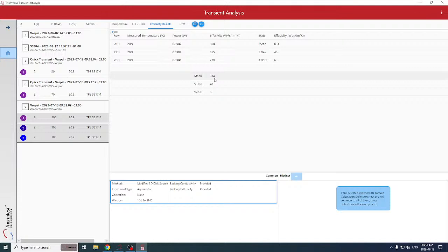That's the end of our discussion today. What we'll do, just to demonstrate the true repeatable capability of this, is run a series of measurements with a little bit longer delay time between each measurement. What does that delay time mean? It means the heat we introduce from each measurement, we don't want that heat from one measurement to interfere with the next measurement. We want conditions to be isothermal. So we'll repeat this and put some data up in the description underneath to show what repeatability you can expect on short time scales.